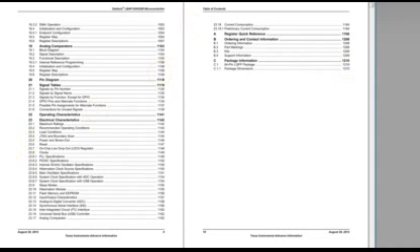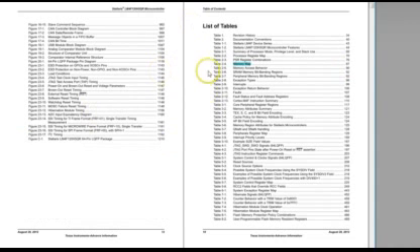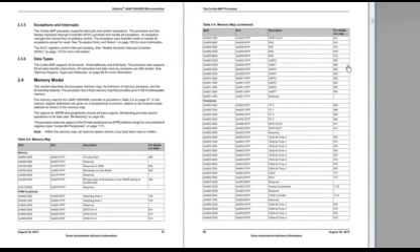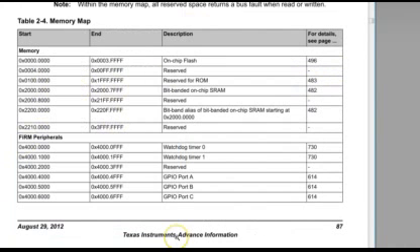So, for example, to find the memory map of your microcontroller, simply search the datasheet for the string "memory map". So here it is, the memory map of a typical modern ARM Cortex-M microcontroller. This is a very nice and simple linear address space without any segments or memory banks. If you work with other microcontrollers, especially the older 8-bitters, I hope you appreciate the simplicity of a linear 32-bit